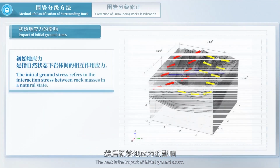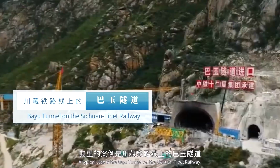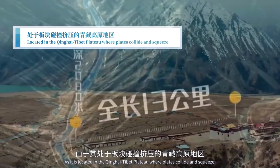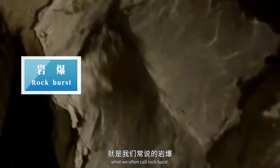The next is the impact of initial ground stress. The initial ground stress refers to the interaction stress between rock masses in a natural state. A typical case is the Bayu Tunnel on the Sichuan-Tibet Railway, as it is located in the Qinghai-Tibet Plateau where plates collide and squeeze. The internal ground stress is extremely high. During excavation, the rock on the wall of the tunnel is crushed by the energy released by the huge ground stress, and the fragments are continuously splashed in the tunnel like shells. This huge and dangerous ground stress phenomenon is what we often call rock burst.